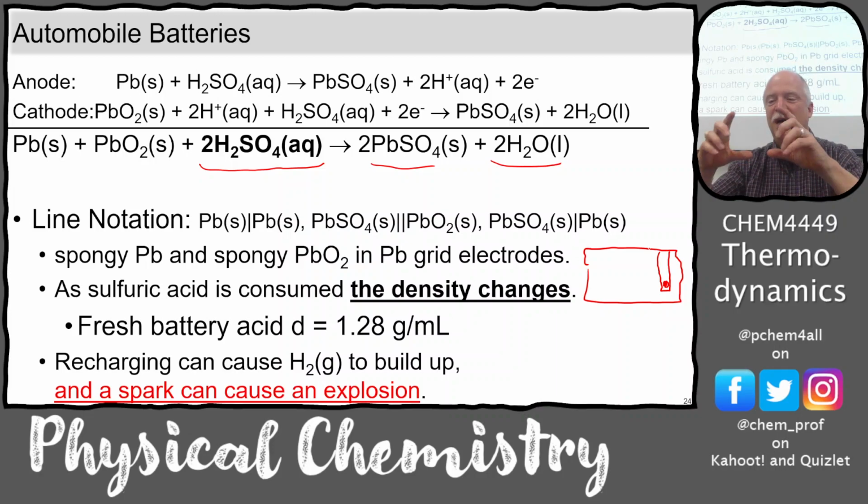Now you can still buy these little density meters that have a bunch of different beads in them, and you suck some of the battery fluid out of the top if you have a battery that can be opened, and certain beads will float and certain beads will sink, and you look at the color code and you say, okay, it's a fresh battery or not.